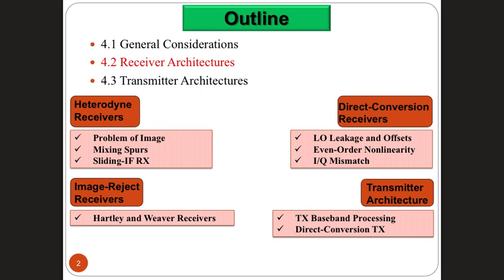But the idea here is, in most cases, you bring it to an intermediate frequency, and then you perform something called an envelope detector, which is simply a diode, resistor, and capacitor. Then that is going to trace the amplitude of the sine wave, and accordingly, it brings the signal down to zero frequency. But in terms of oscillators or multiplication by other frequencies and so on, you don't bring the signal all the way to zero frequency. This is the whole idea of the heterodyne receiver.